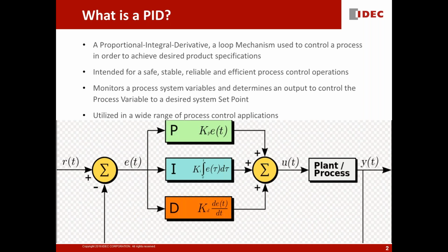That's what PID is. It's the graph I'm showing you this morning. It shows a closed loop where you have the gain, the proportional term, the integral term, the derivative term. You have the error, and every scan time you look at the error and you adjust your output accordingly to make sure the set point and your process variable are equal, basically.